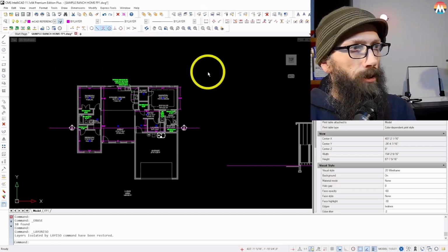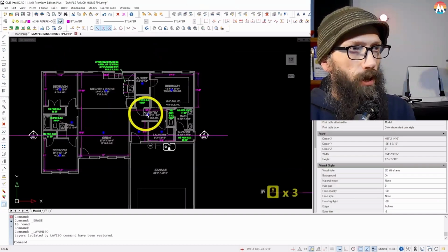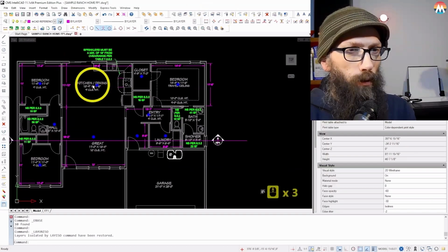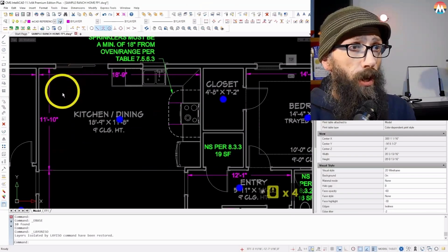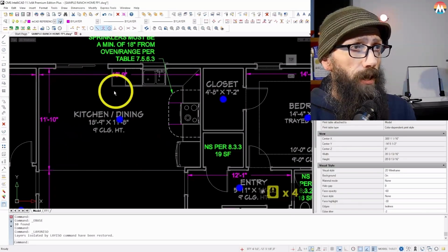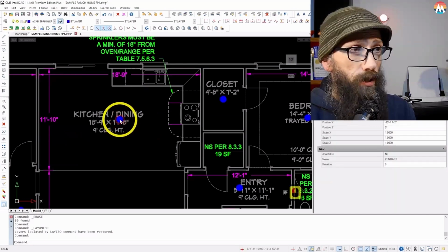Okay, so we have the heads dispersed, but I don't know if you remember, I mentioned the spacing was 16 by 16. And here we've got a box that's 18 foot wide. So we need to spread them out in here. We need two heads in here.